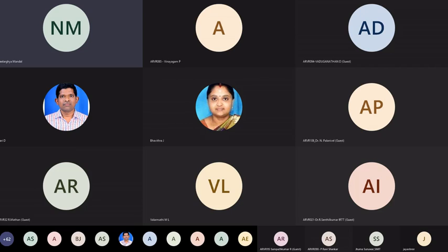Okay, so when it comes to CAD models, normally they are pretty simple to import into your game engines or AR/VR building software. The issues that they normally have are with the texture mapping and the UV mapping. If the texture is recognized by the game engine that you're working with, it's very easy. It's mostly like a drag and drop or import. But if the textures don't get mapped properly, you might have to work inside of the game engine to remap those textures.